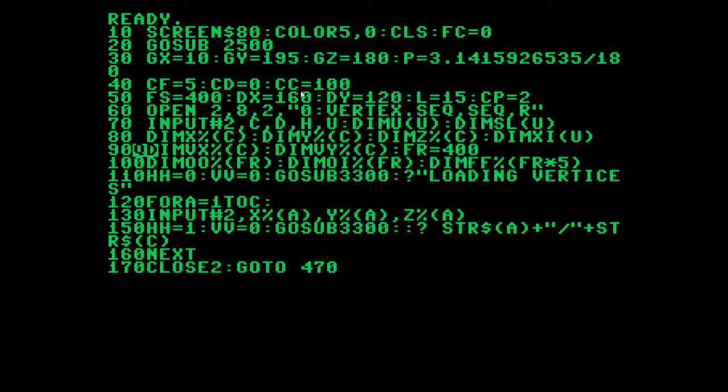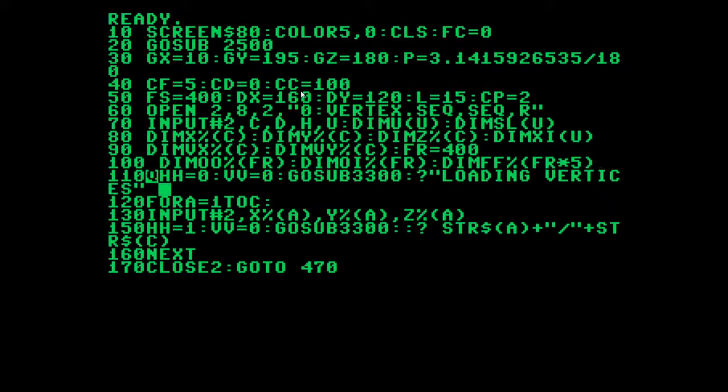So why did I delete the spaces? It's very simple. The code and the model data share the same memory, and the code is written in ASCII characters, and every ASCII character needs 1 byte, even the spaces here.